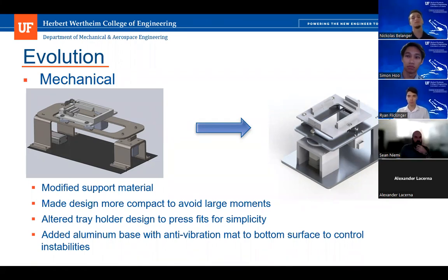The main reason for that was because we originally had it made out of sheet metal, as you can see over there on the left, and that made it hard to manufacture because that is a very thick plate, and we didn't have the tools to really make those bends in house. So we went to a more robust design with the U-shaped base made out of 6061 aluminum, as you can see on the right.